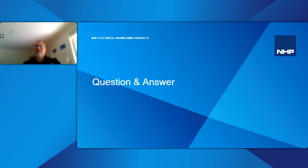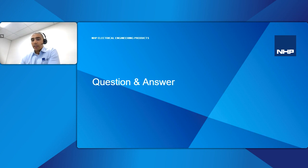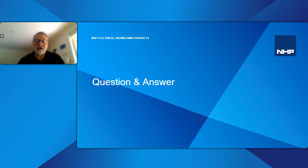I think that answered as well the next question, which is, can the FactoryTalk Policy Manager rebuild from uploading from the network? No, you can't upload the policy out of the network. It's not like source code. It's source code down, not source code up. You can't pull it. It's not like uploading an ACD file.